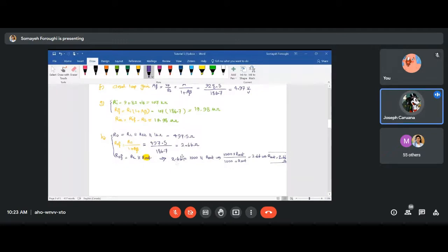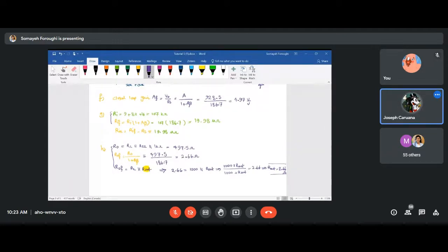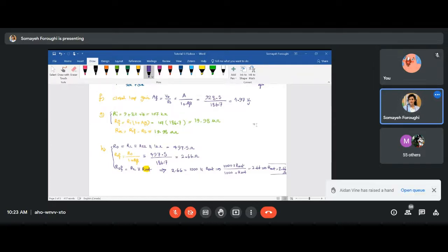Is it basically the same principle as the resistance reflection rule? If you go back to the lectures, you have different configurations for feedback. You have shunt configuration, series configuration, and each of which has a set of equations. For example, what we have here is not shunt, it's series, and then you have your RIF like this equation and ROF like the one in the bottom, the orange one.